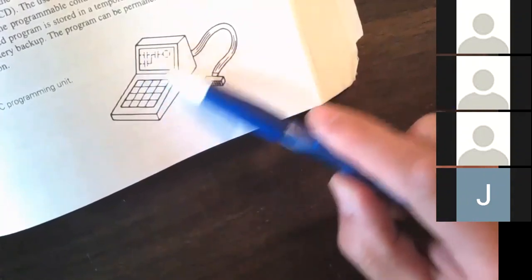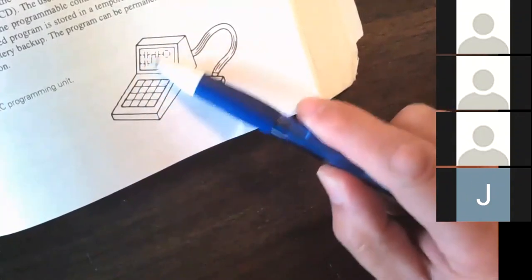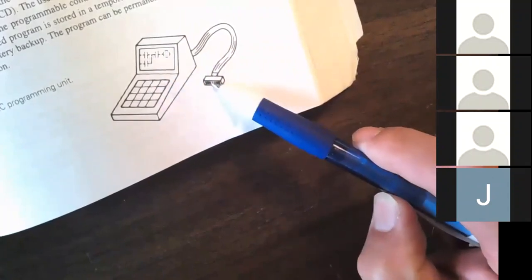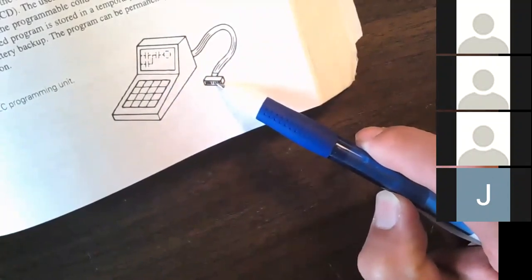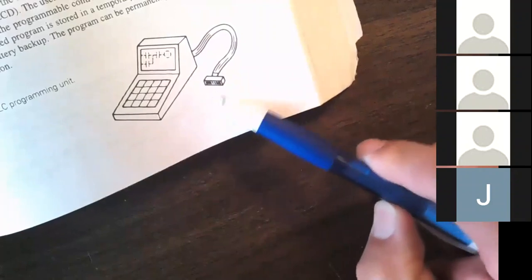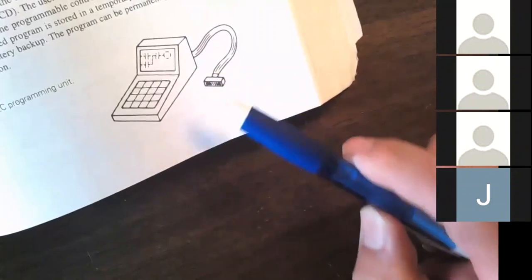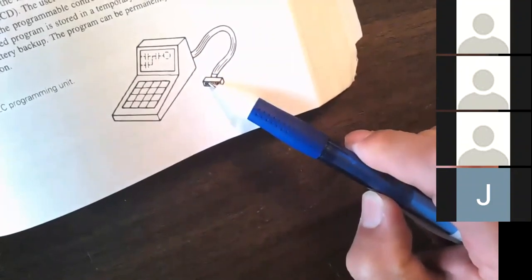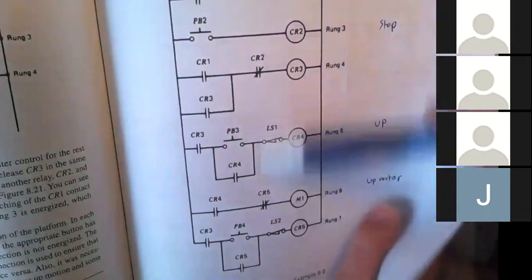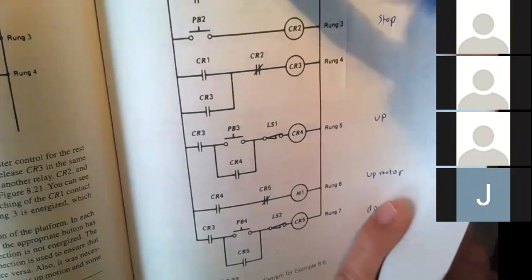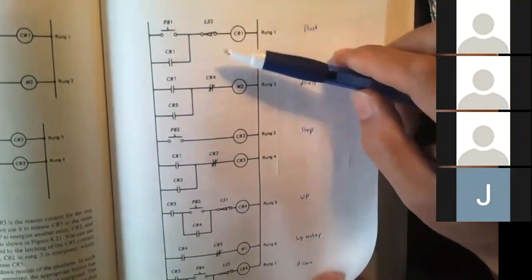Once the control engineer finishes programming the ladder diagrams, it will hook up to the PLC and download the program to the PLC. Once the program is downloaded to the PLC, you are done. Then you can start testing. So that's quite an advantage compared with before.